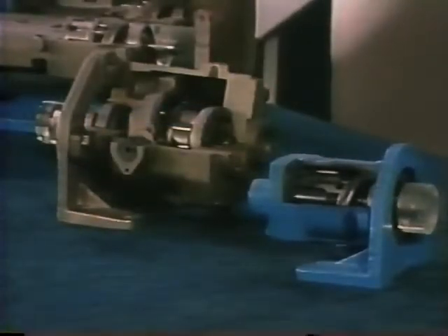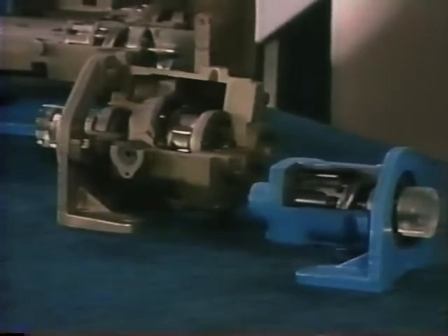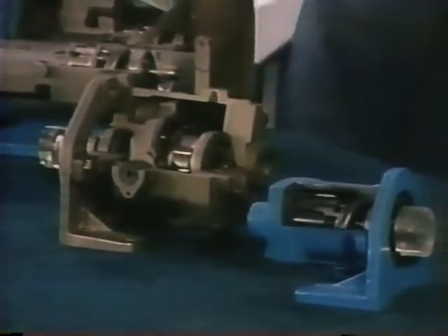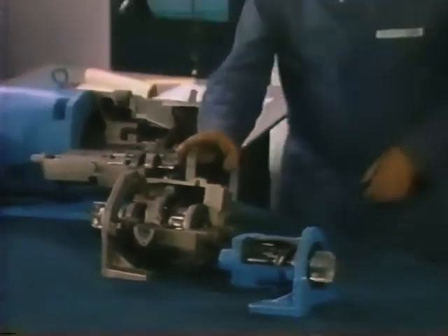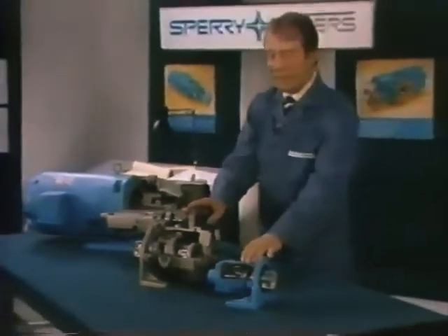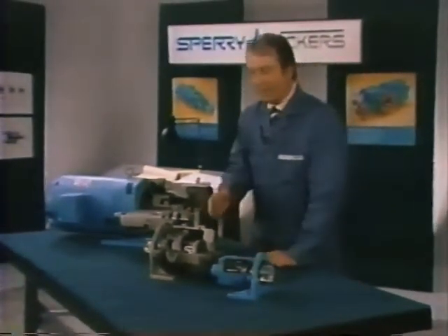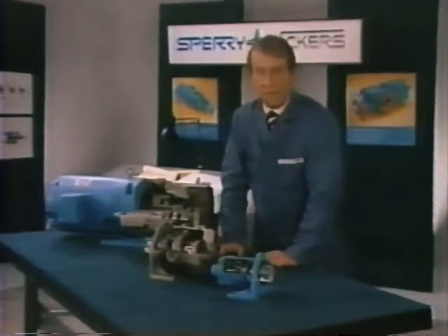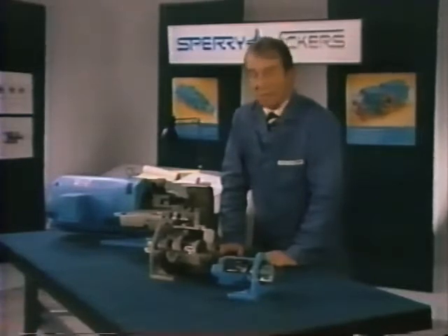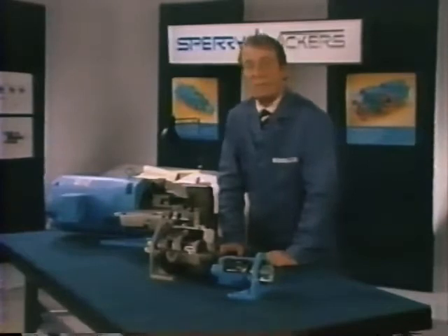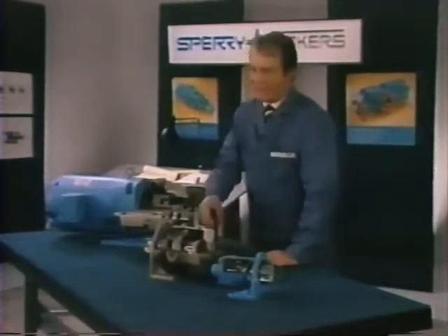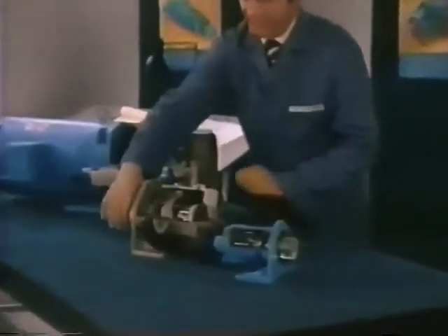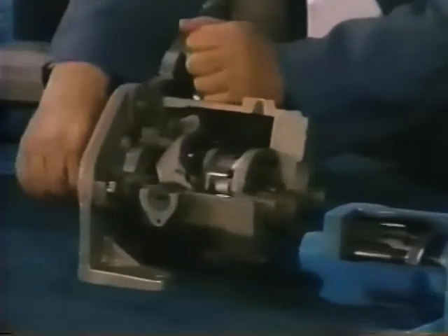Here we have 2 cutaway models of the units we've been discussing. This one is a variable displacement pump, and here we have a fixed displacement motor. The pump has a lever which can be operated manually to move the yoke. The yoke holds the swash plate in any desired position from maximum displacement in one direction through center to maximum displacement in the other. As the shaft is rotated, we can see the pistons withdrawing from their bores.